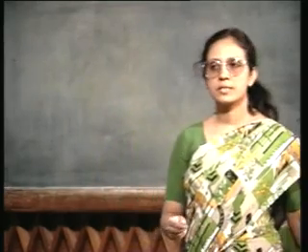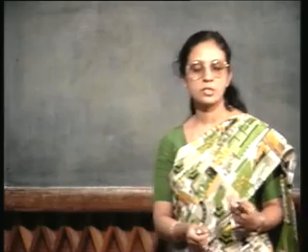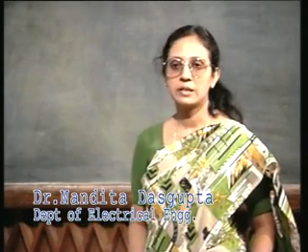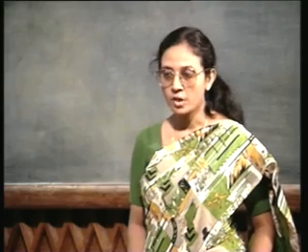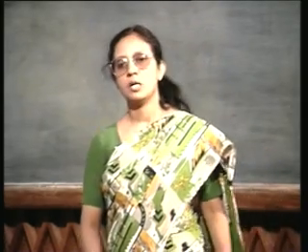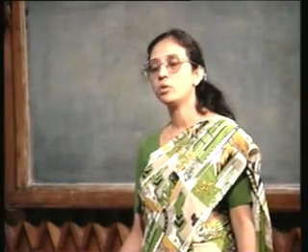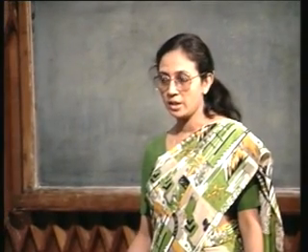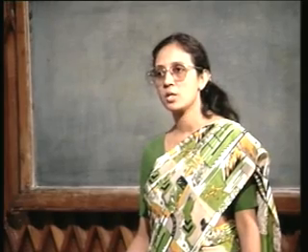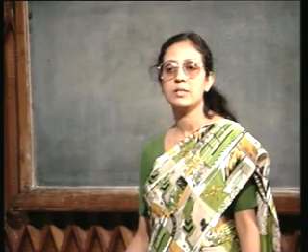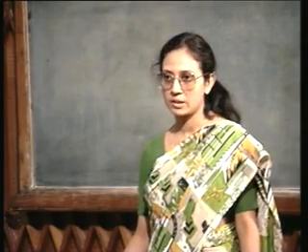So, we have been discussing the different processing steps used in fabricating a bipolar junction transistor in an integrated circuit. We have started with an NPN transistor. We have seen how the isolation between the transistors has to be obtained, either by junction isolation or by dielectric isolation. In dielectric isolation, you have also seen low cost as well as trench isolation, and then we have said that it can even be done by using selective epitaxy.